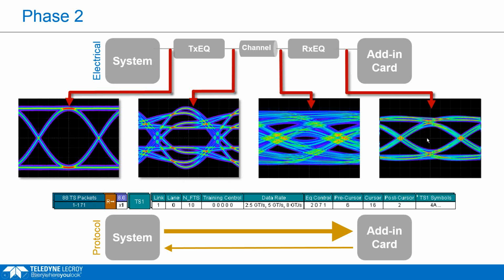It's always done on power up, but if a lot of bit errors are detected, it can retrain at any time. If you bump into it and something happens, or if the temperature changes, it can always go back through recovery and redo all of this optimization. Also, if it goes through a couple of times and can't find settings that work, it can retrain to a lower speed and go down to 5 gig.